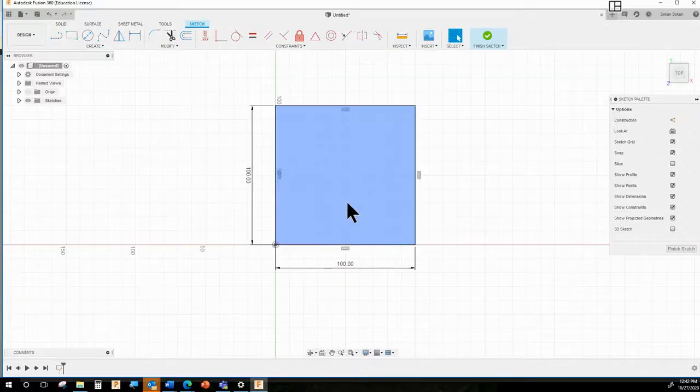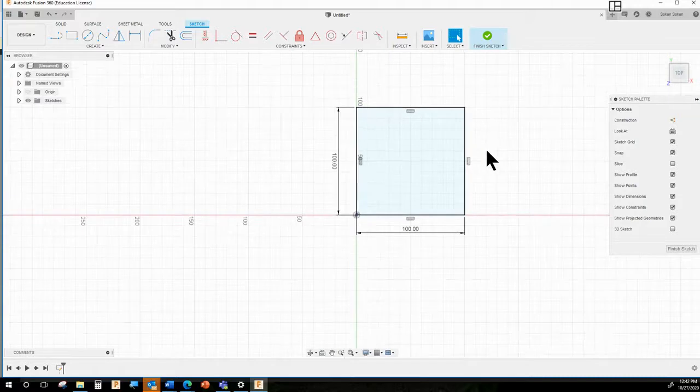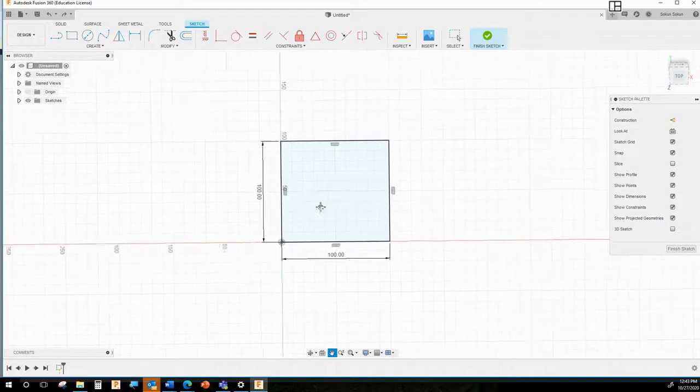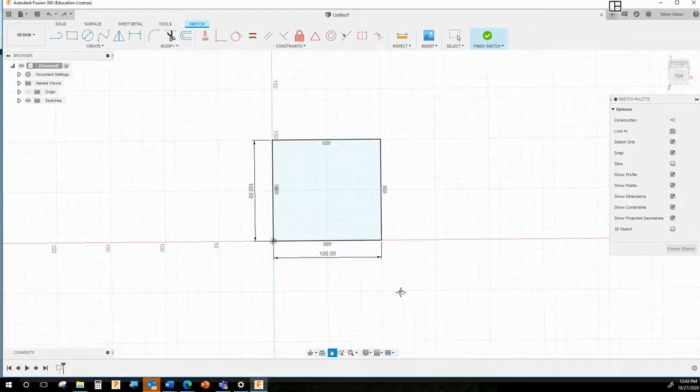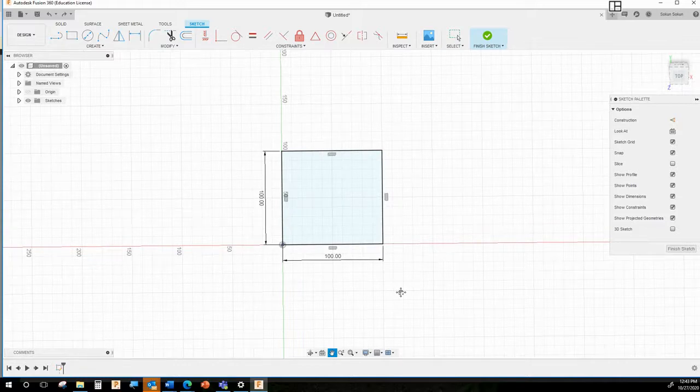And you'll get used to it over time, and it really does become a nice, powerful thing. At first, it might be frustrating. The other thing you can do is pan. And pan is a little hand down here. So just click on the little hand tool, and then you can move around like that instead. You can still zoom in and out. Just remember you're in pan mode now, so if you use the mouse, you'll be panning in and out.